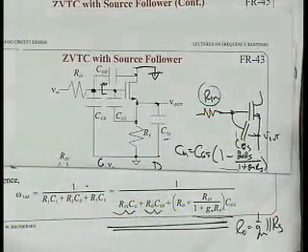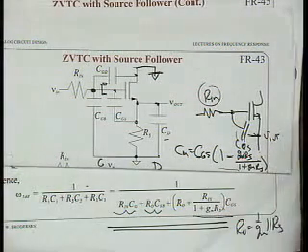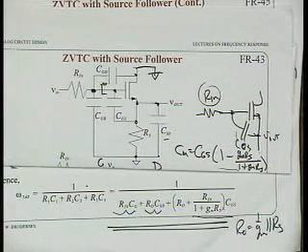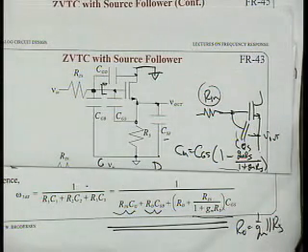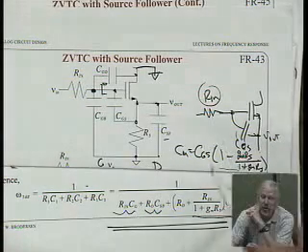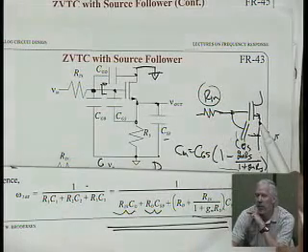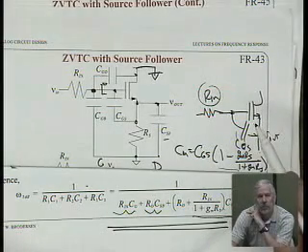What about the second pole? Unfortunately, as we're going to learn in a few weeks, a month, it turns out for stability, the first pole, what we'll do is make it to be very low frequency, so we can make the circuit stable. It turns out it's the second pole which is actually the really important one for setting our frequency response. In fact, we'll have to fool around with the first pole depending on where the second pole is. So it turns out what you really need to calculate is the first two poles. This tells you nothing about the second pole, the next highest one. That's just the way it is.